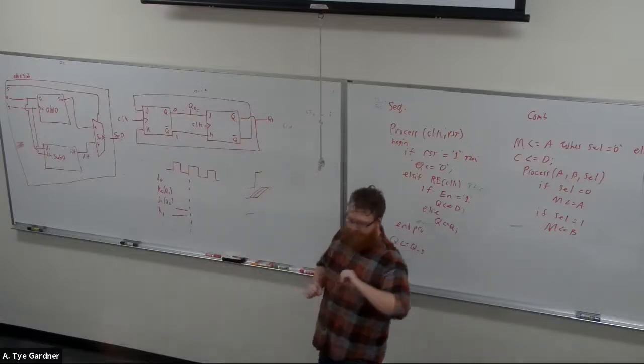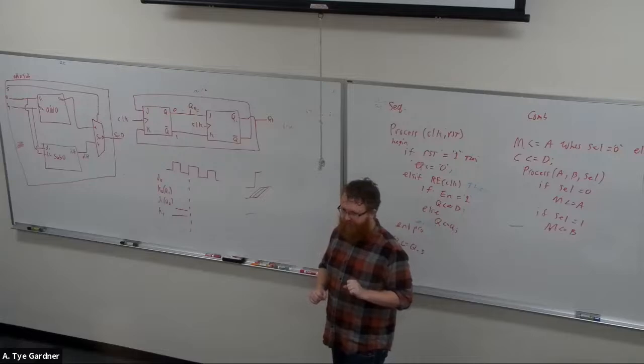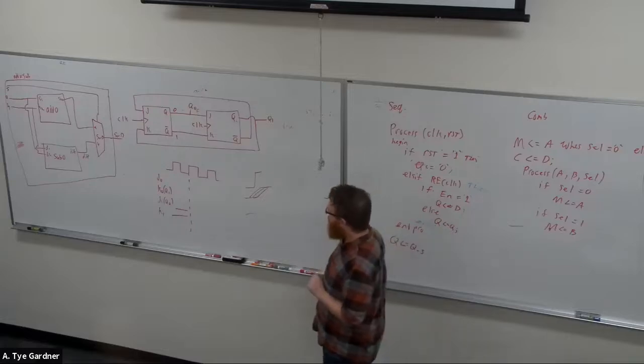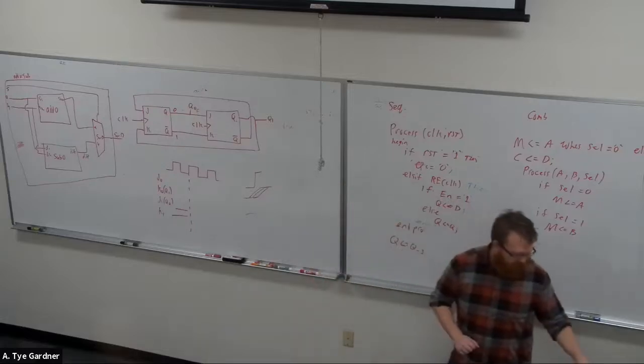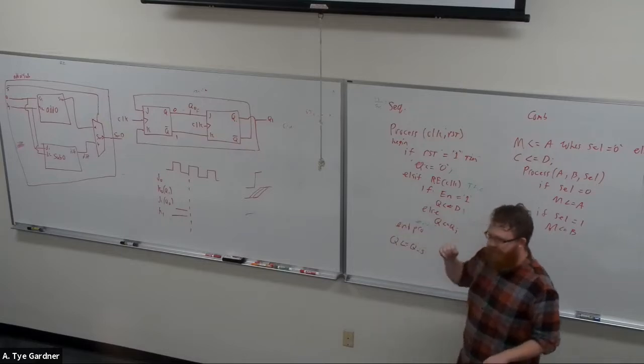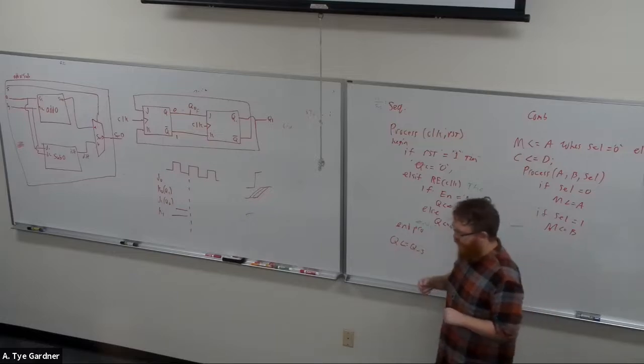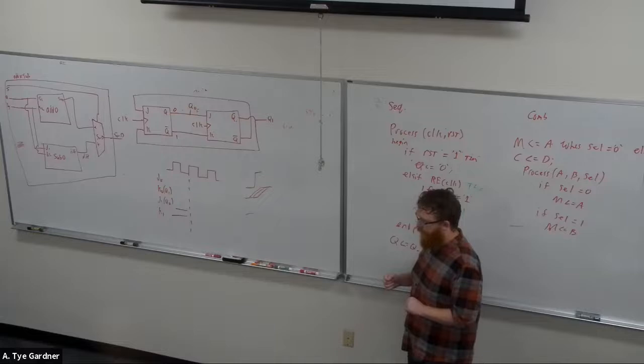But at this point, because we've talked about setup and hold time and clock to Q delays, right? I could have a flip-flop where I give you a timing diagram and say this has a setup and hold time of 10 nanoseconds, and a clock to Q delay of 20 nanoseconds or something like that. Draw the timing diagram, right? And if the rising edge comes at a time